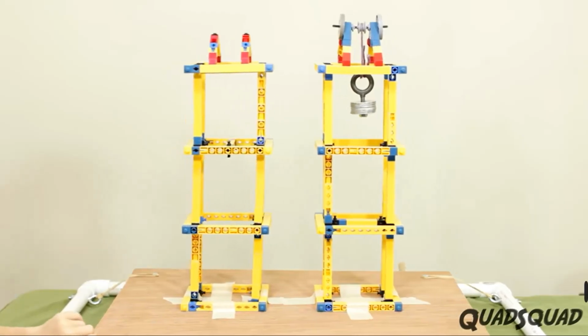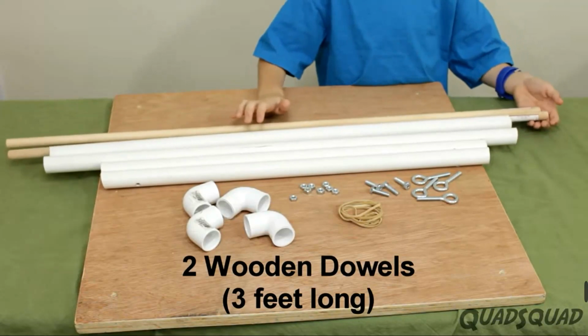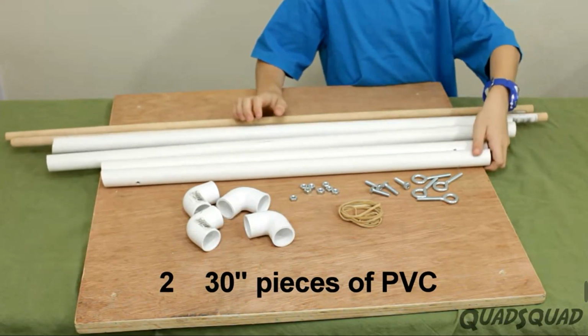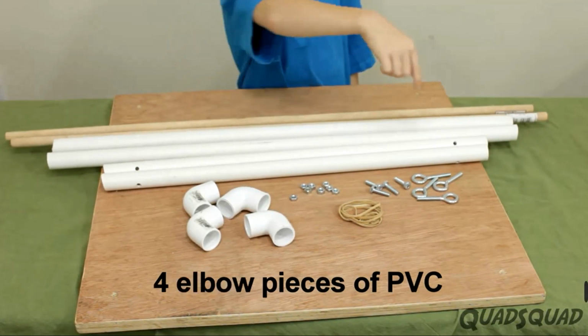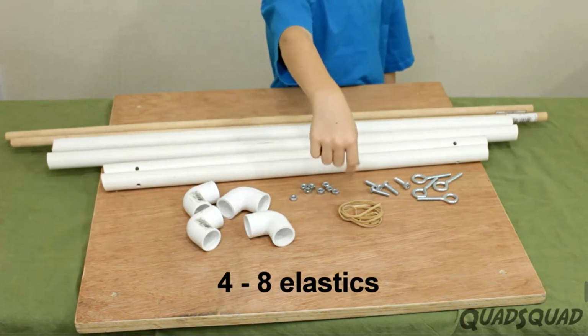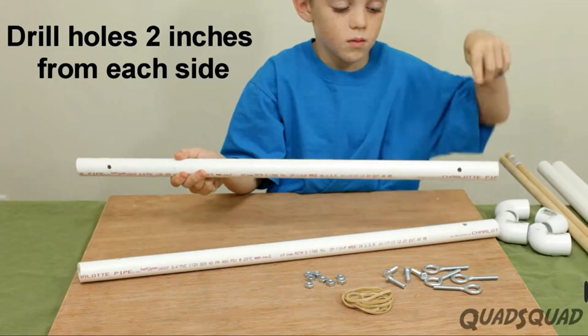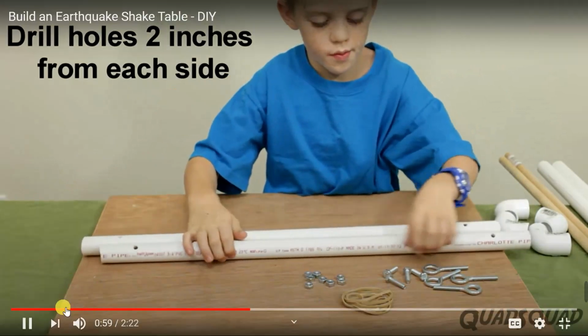Hi, my name is Justin. Today, I want to show you how to make a simple shake table. This will be helpful when you're testing a building that you've designed to see how earthquake resistant it is. You'll need 2 wooden dowels that are 3 feet long, 2 30-inch long pieces of PVC, 2 24-inch long pieces of PVC, 4 elbow pieces of PVC, 4 eye bolts, 8 nuts, 4 bolts, 4 elastics, and a wooden board that's 24-inch by 24-inch. Let's put it together. Drill 2 holes in the 24-inch long PVC pieces. All my PVC pipe is 3/4 inch.